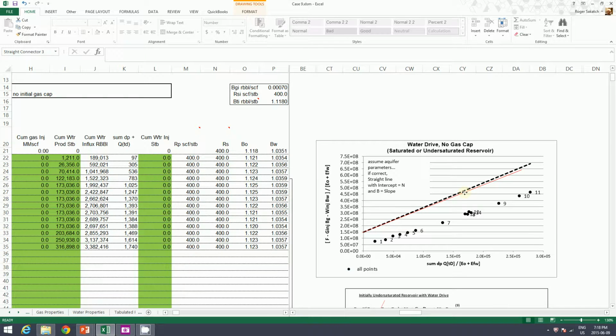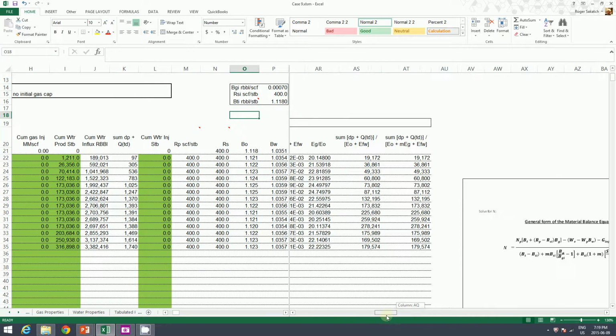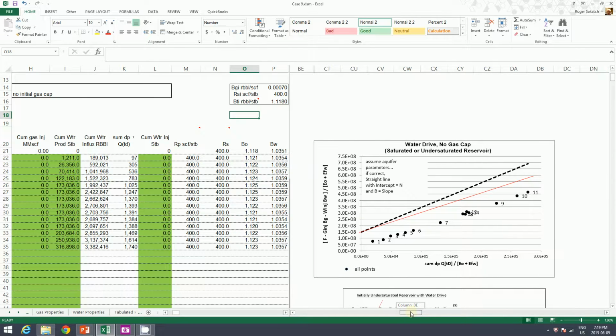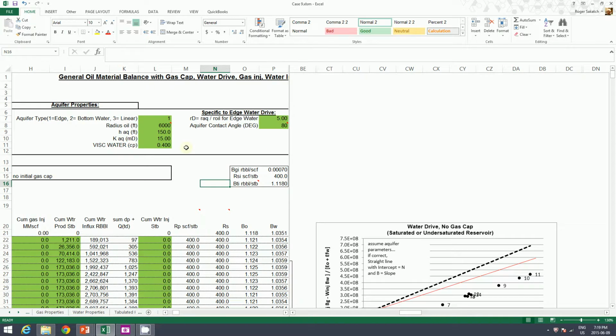That slope is a little bit off, and that would be the correct line. If we were to pull that up, there it is. The slope is quite a bit off. That tells us again that a permeability of 10 millidarcies with those other parameters in place just doesn't seem reasonable. So I'm going to put that back to 10.5.